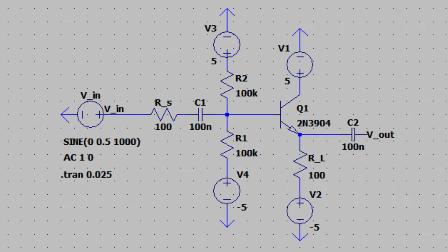To determine the values of certain variables, many calculations had to be completed. I first started off by solving for Gm by using the equation V internal is equal to 0.2 multiplied by V thermal, which is multiplied by 1 plus RL times Gm. And after rearranging and subbing in the values of 25 millivolts for V thermal, 0.5 volts for V internal, and 100 ohms for the resistance at the load, I could solve for Gm to be about 0.99 S or 990 mS.